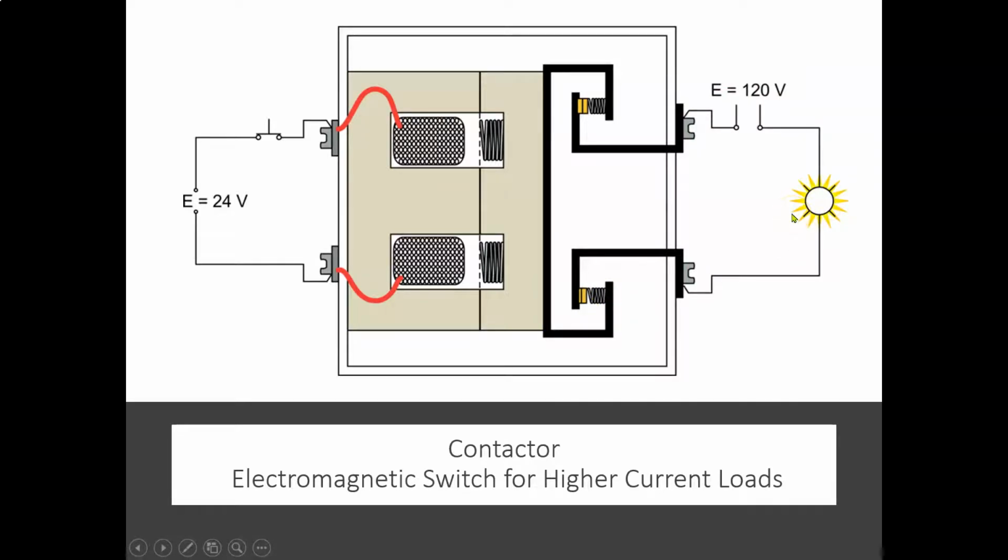The purpose of these springs here and these springs here are 2 different purposes. When I have a lot of current flowing in a circuit and I try to break that circuit, I have arcing, and I want to try to limit the amount of arcing. That's why they have maybe 2 sets of contacts, or bridge contacts. When the current is cut from this coil, so this push button is opened again, the current is cut from here, so the magnetic field is going to drop.